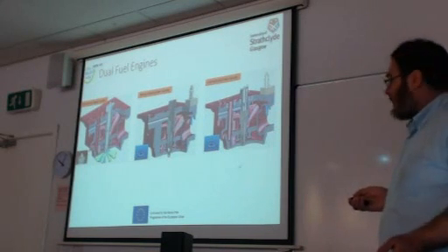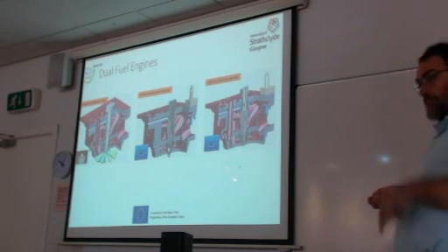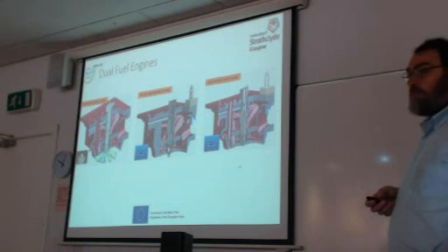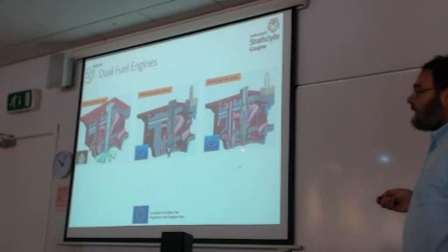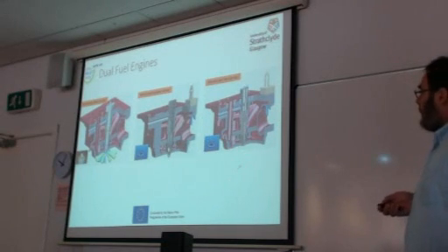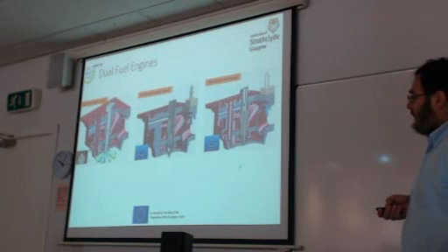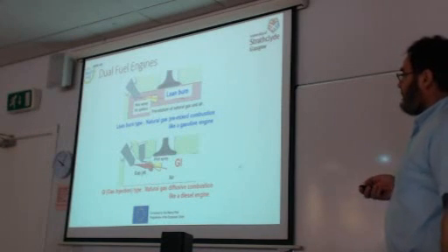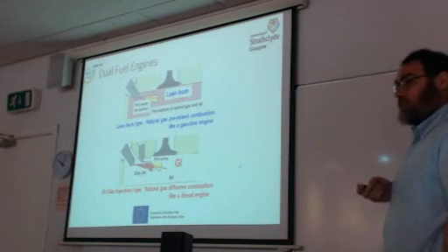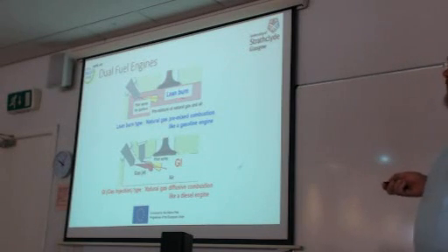And then there is the dual fuel engine concept, and in this case we have, of course, two fuels. We have the natural gas fuel, the gaseous fuel, injected either in the port or directly in the combustion chamber. We'll discuss the difference later. And in this case, we need a pilot fuel, usually diesel oil, that is injected within the combustion chamber, and of course provides the initiation of combustion.